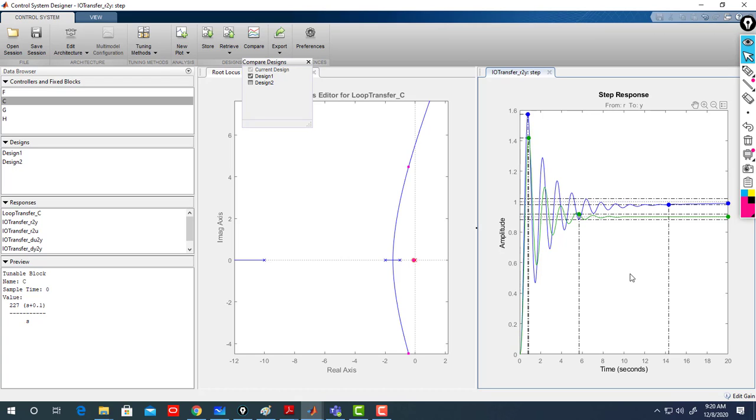So basically you see the difference in errors. This reached steady state better than design 1, which is without compensator, and doesn't affect the transient response, in the sense it doesn't affect the overshoot of the system. It affects the settling time but doesn't affect the peak time and the overshoot. So I have the same overshoot 57, 57, and the same peak time. So that's the transient response characterized by rise time, peak time, and overshoot.